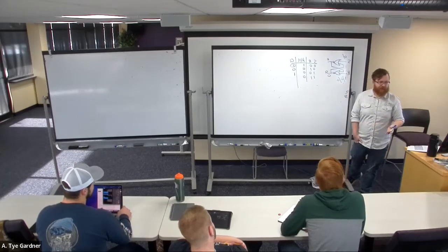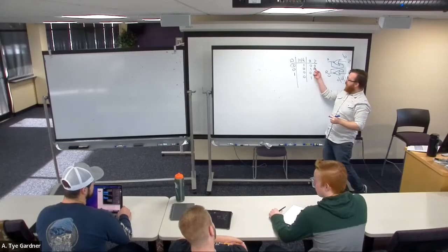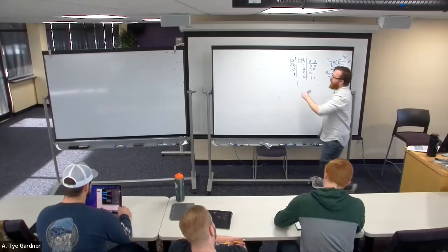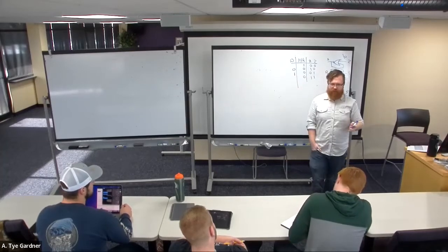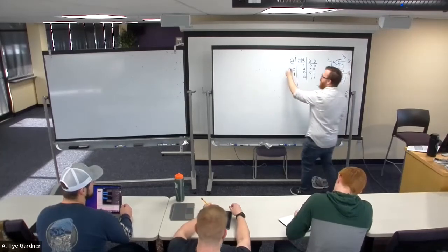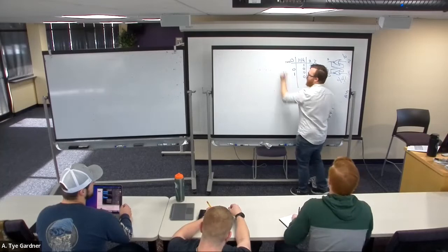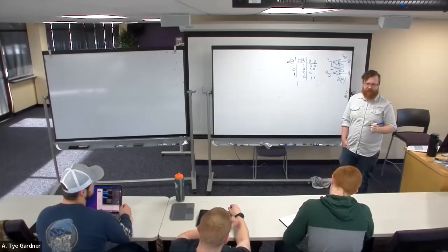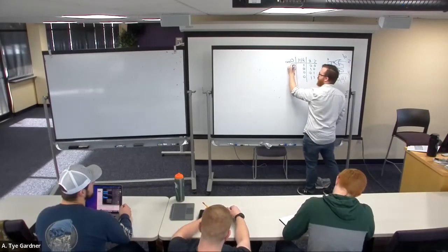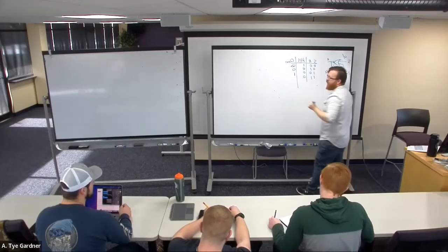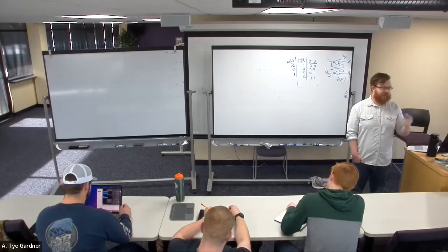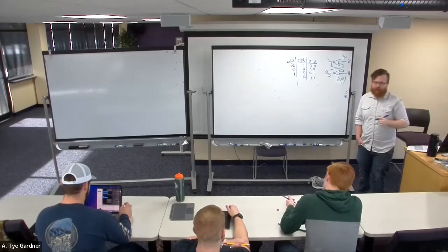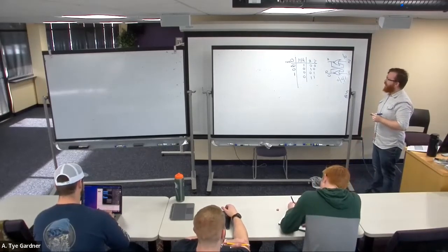Nothing happened. Okay, so in the case where I am neither having S or R, it's not 1. It turns out that I need a new kind of notation, which is to say my next Q, Q(n+1), is my old Q. It stays, it remembers what it was, which is really quite convenient.